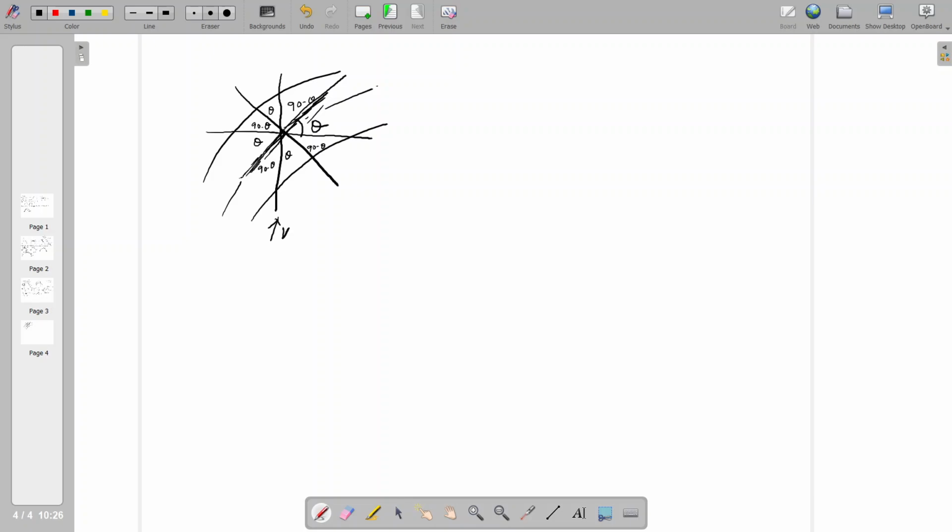Normally the Vx will be in this direction and Hx will be in this direction, and the normal to the plane, this is the normal line. So the normal to the plane of the arch is Nx, and along the radial line it is Rx. So we are going to calculate Nx and Rx with the help of Hx and Vx, because from the given geometry we can easily find the vertical reaction and the horizontal reaction. From Hx and Vx we can calculate Rx and Nx.